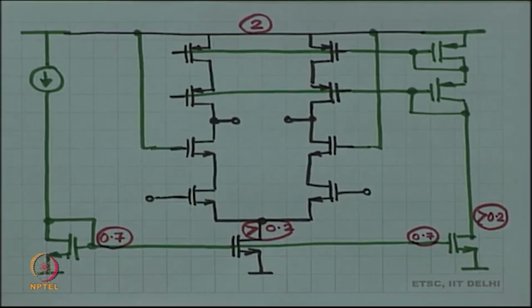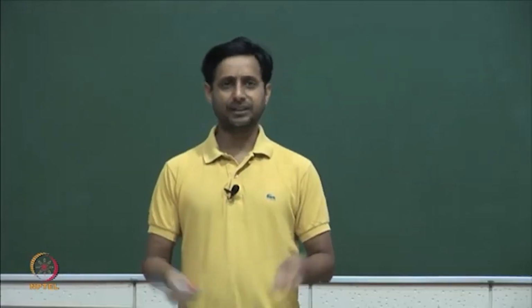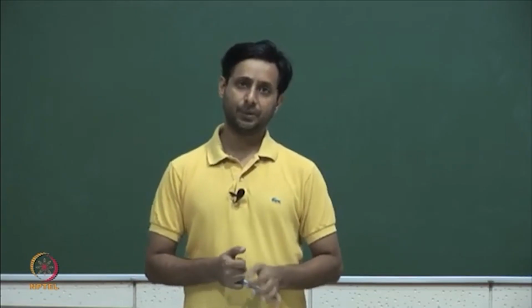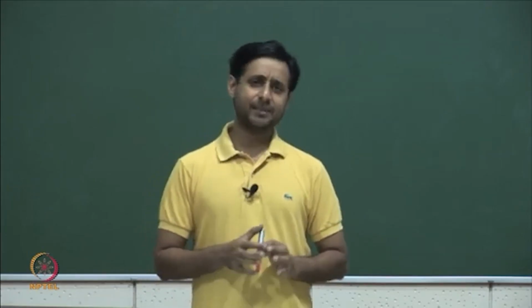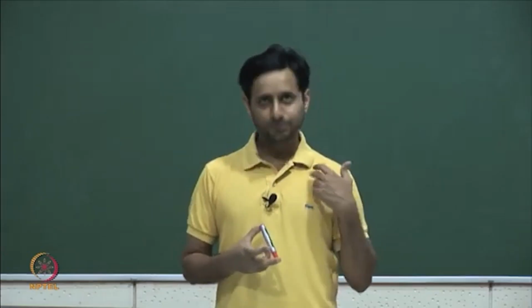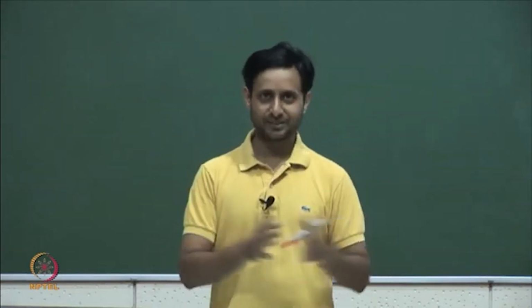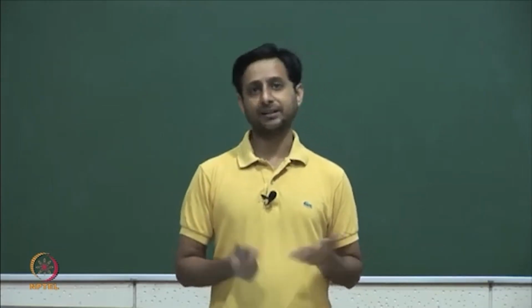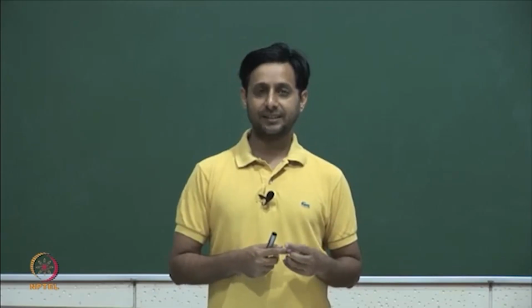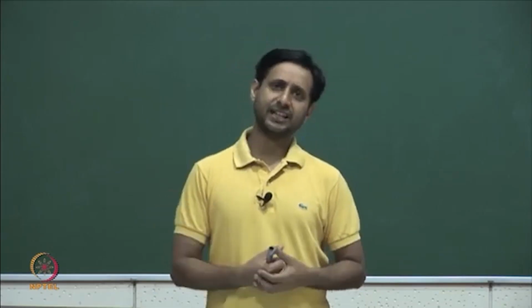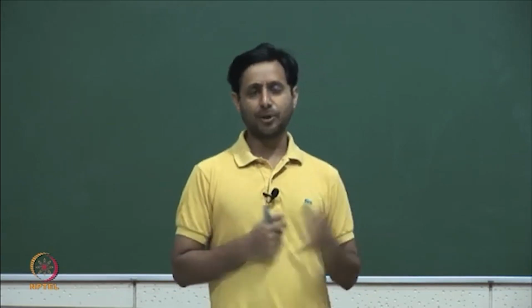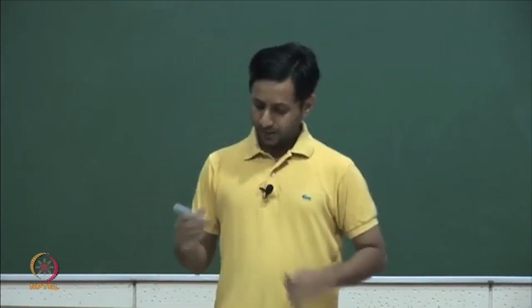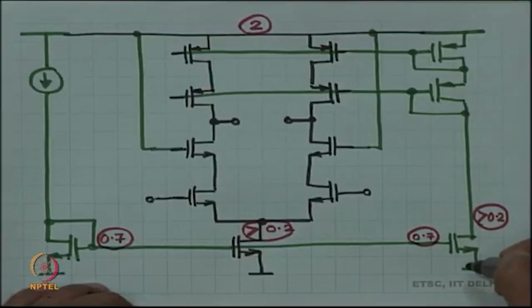All right. And let us say that the PMOS also happens to have a VT of 0.5 volts. Okay. You want a different number? Okay, fine. Let us say the PMOS has a VT of 0.4 volts. Okay, just throwing numbers. So, 0.4 volts of VT, and I would like the PMOS to also have a VGST, that is VSG minus VT of 0.2 volts, which means that I want VSG, the source to gate voltage, to be about 0.6 volts, which means that when I pull this I naught by 2 of current,